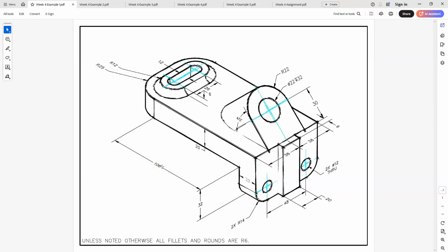Now, before we get started, I just wanted to make sure that we do a little bit of calculating, and you can see that the distance between here to here is 106, right? Now, when I create this shape, I have to account for that extra radius part that's back here. So I'm going to have to add 25 to the 106. So that gives me a number of 131. Some other things that you can see is that there's a distance that goes between here. And you can see that that number is sitting here at 26. So we do have that distance that's going across from here.